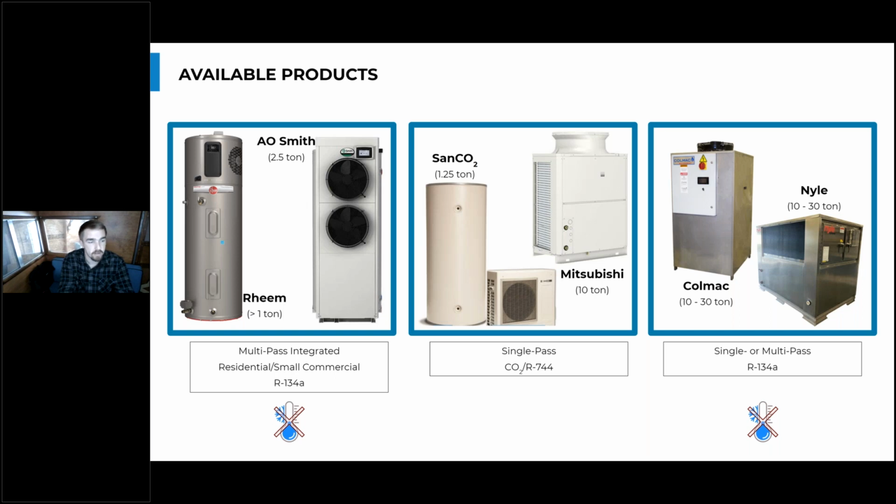So the first category that we've created here is the multi-pass integrated heat pump water heaters. They're more specific to residential or very small commercial applications, simply because they don't have a really high recovery rate or really high capacity. So they're more suited for residential or small residential applications, right? And these heat pumps have everything built in. They have the storage and the heat pump together, so you don't have to worry about the extra plumbing. So this heat pump is more like one you would see being sold at a big box store and installed maybe in your garage or in your basement to heat your water.